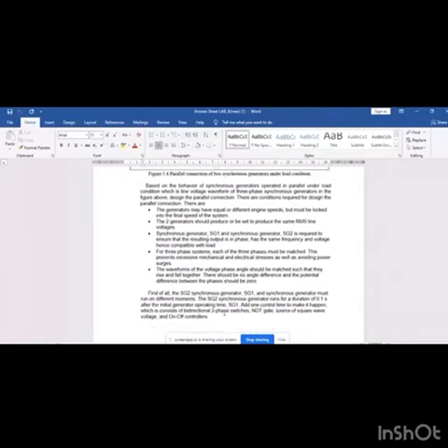For the steps, first, synchronous generator 1 and synchronous generator 2 must run at different moments. Synchronous generator 2 runs for a duration of 0.1 second after the initial generator operating time of SG1. Add on time to make it happen, which consists of a bidirectional three-phase switch, NOT gate, source of square wave voltage, and on-off control.